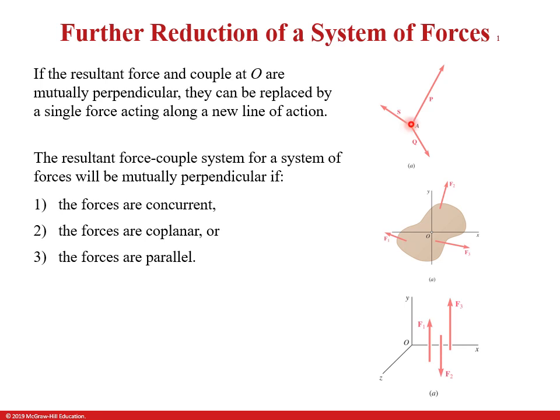where either the forces are concurrent, sorry. The concurrent forces are just acting on the same point, right? All the lines of action pass through the same point. Coplanar forces, they all act in the same plane, right? So notice they're not concurrent. They don't all pass through the same point, but they are acting in the same plane. And then parallel forces. So in 3D, if the forces are parallel, right? So notice F1, F2, F3, these two are pointing up in the vertical Y. This is pointing in the negative Y. These are all parallel forces in 3D.